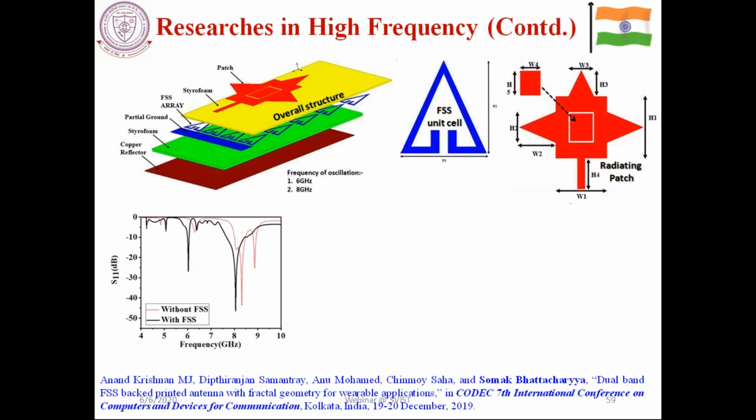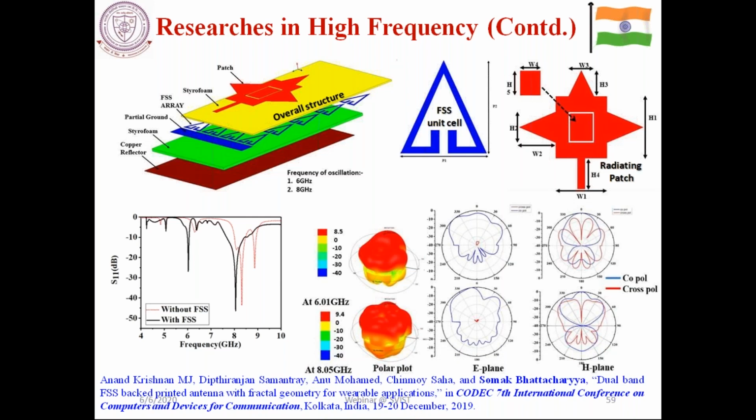And what you can see is that you don't want any radiation towards the body. So if you see the spectrum over here, you see the back lobe has been significantly reduced. So this is the main application of this particular antenna, where the back lobes can be reduced.